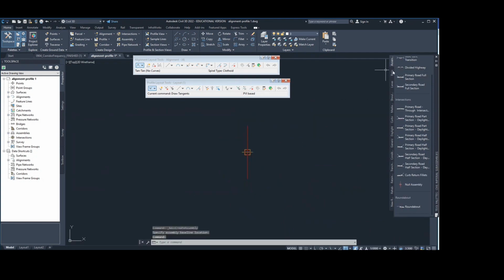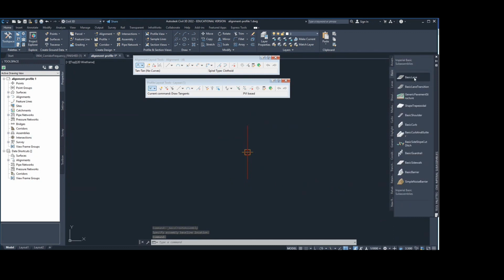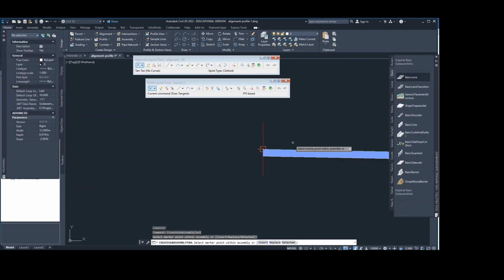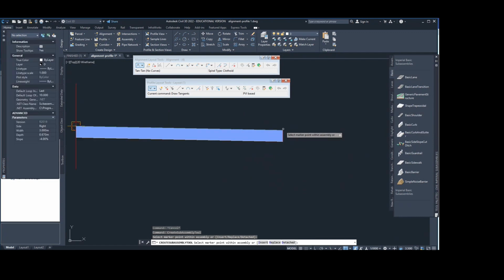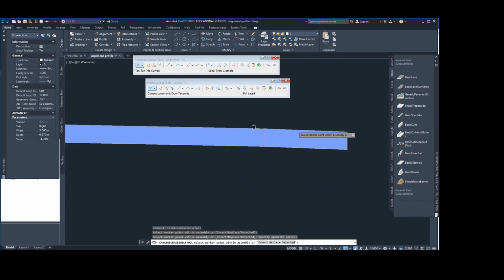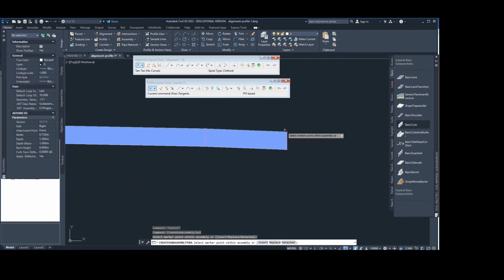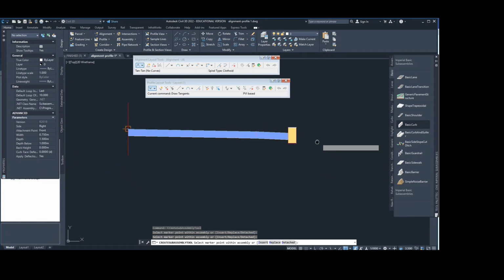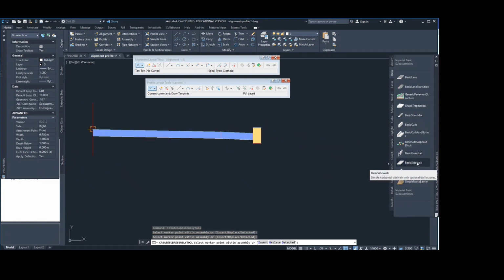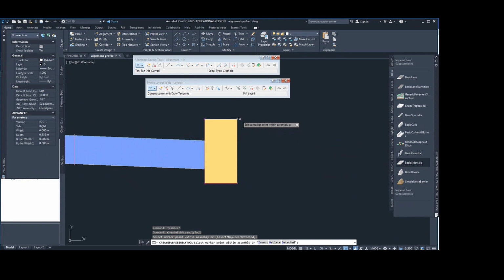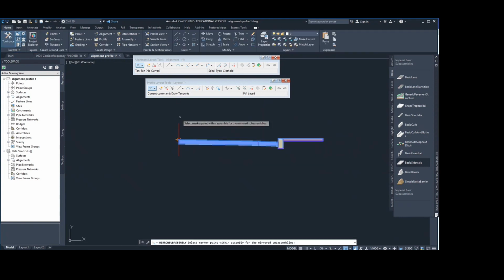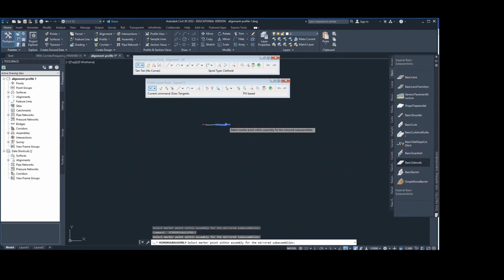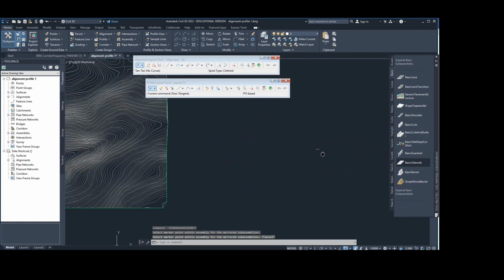You can create your assembly by going to Basic. You can add Basic Lane, Basic Shoulder, Basic Curve. Also, you can add the Basic Sidewalk and make it complete by selecting it and mirroring. Now you have this assembly.